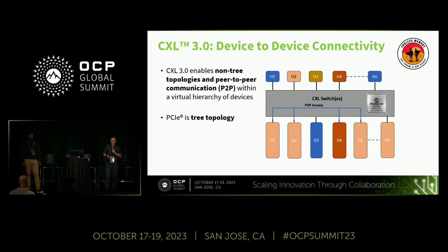So if you look at the interconnection for CXL compared to PCIe, PCIe is a top-down topology, so it's more like a tree. And even though with our current Gen 5 PCIe switch, we allow customers to build a complex fabric through what we call the advanced fabric switches, and that gives you more flexibility to connect, like host to host, SR-IOV and multi-host interfaces. That means you can connect one domain of host to the other domain endpoint or the other domain of host.